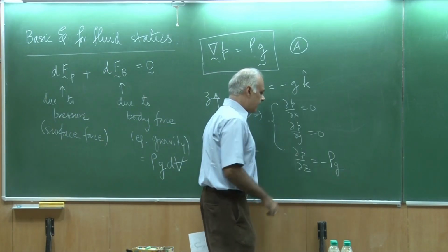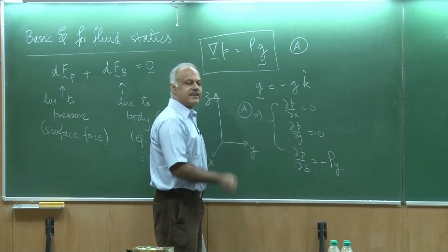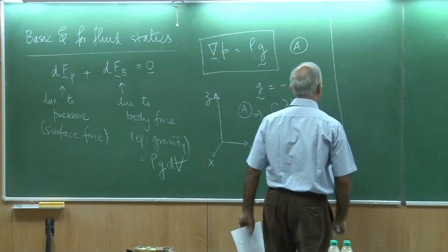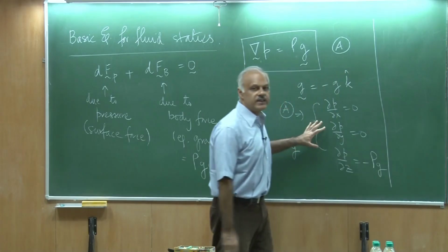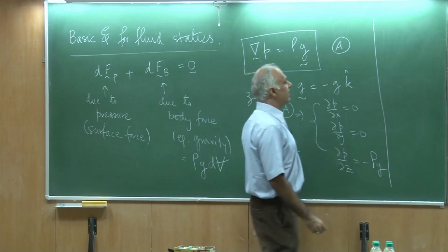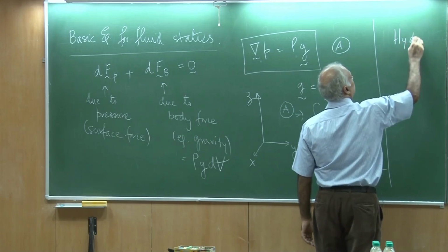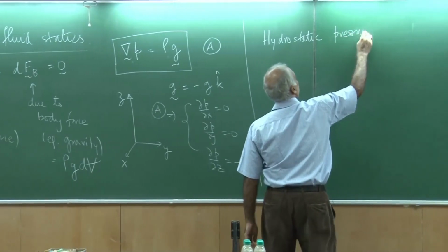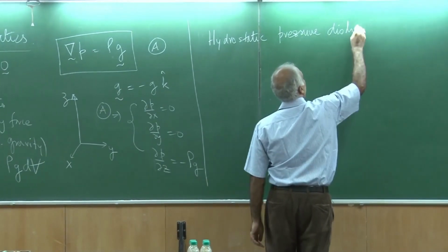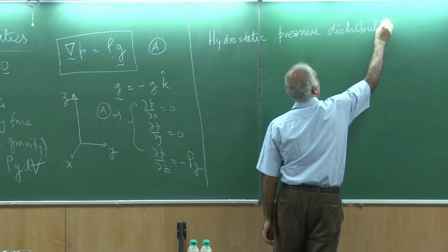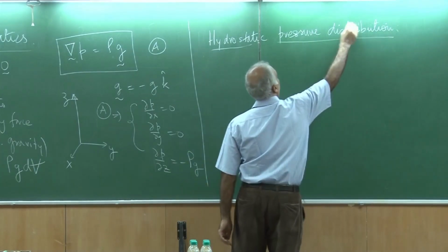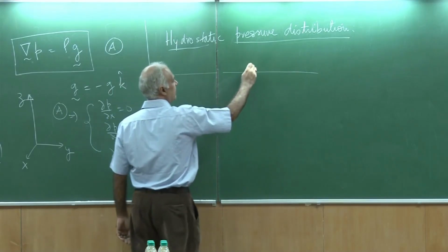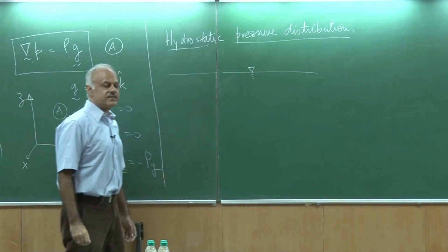So one can look at the forces on a body by simply integrating these three equations. So using these three equations, I can talk about hydrostatic pressure distribution. So imagine I have a fluid and this is the free surface.